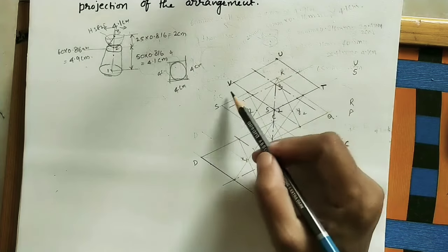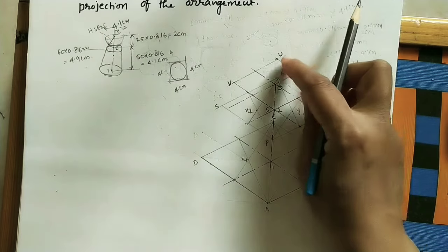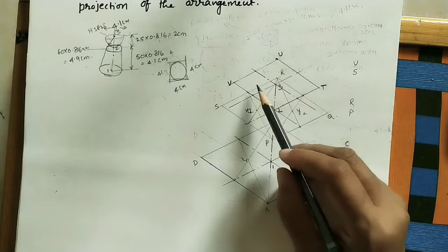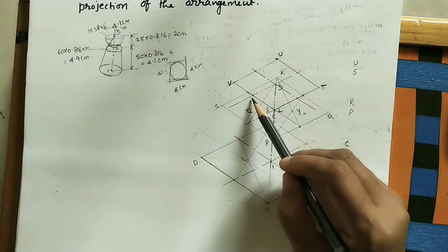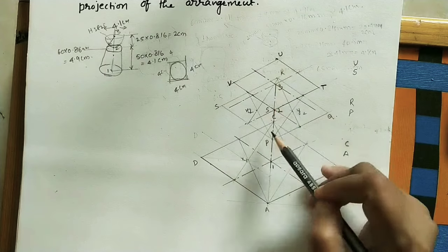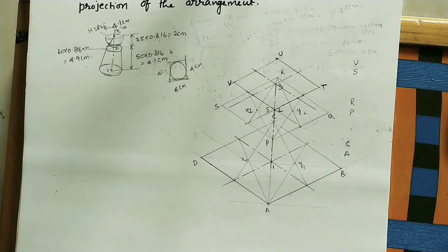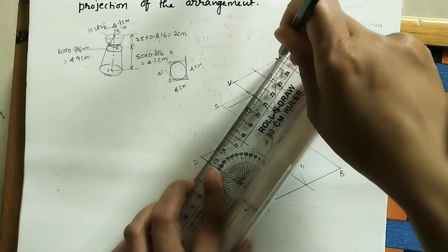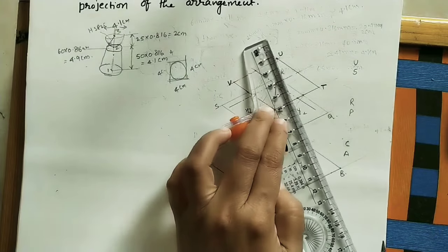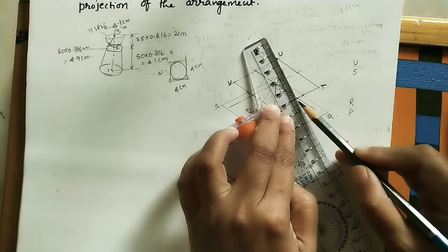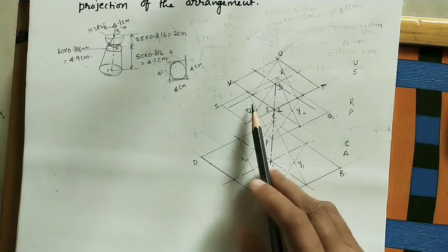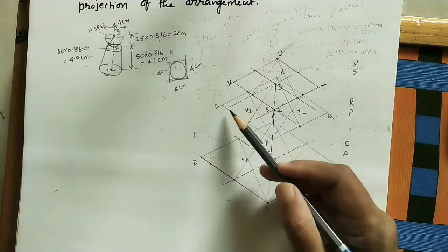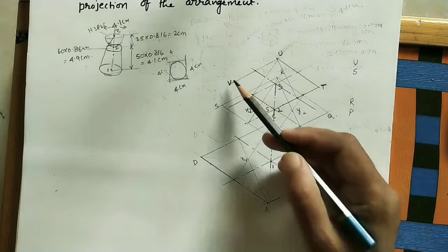Now similarly in this rhombus also follow the same. Shorter length ends are U and S. Join U to the opposite middle points. What are the opposite middle points? For this side, the middle point means this one. Join this point to U and join this point to U. So these are the middle points. You can ask how to find the middle points, means no need to find, wherever the axis line is passing through this line, it is a middle point.